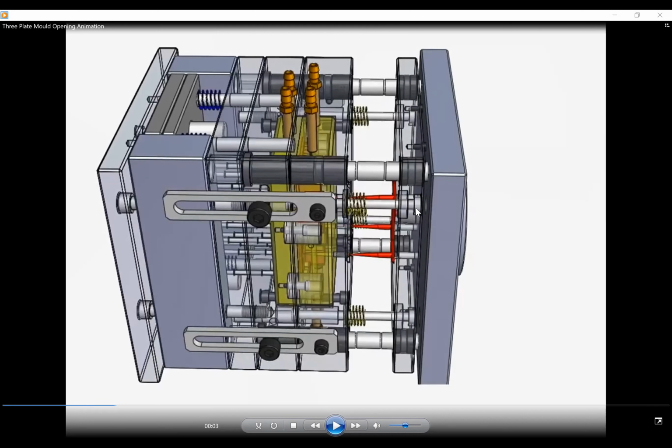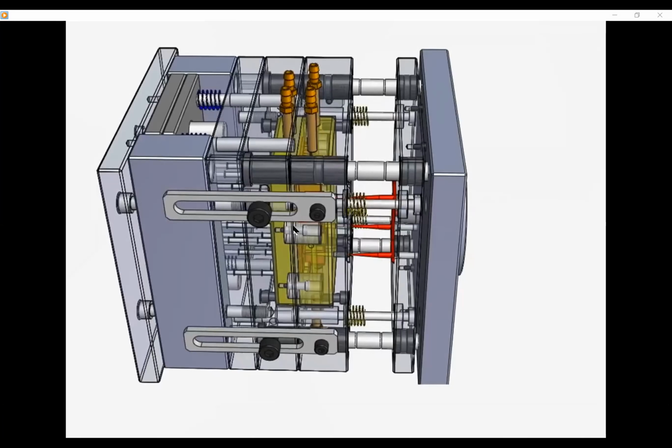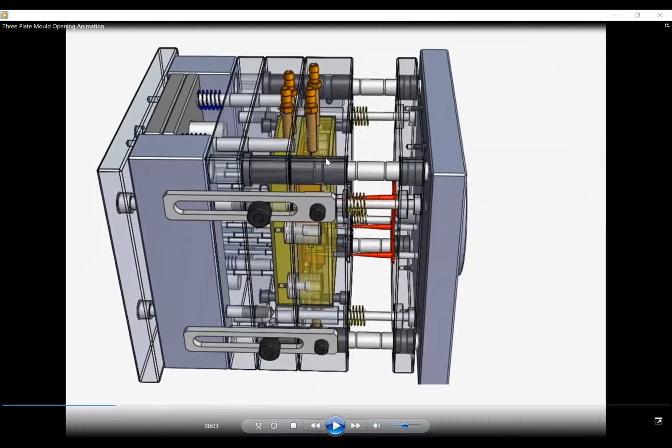Actually there are two sprues. One sprue is coming from the extrusion screw, and then that distributes along all the materials. It can be a single large part, or it can be very discrete parts. For discrete parts, you need an injection sprue line for each part.